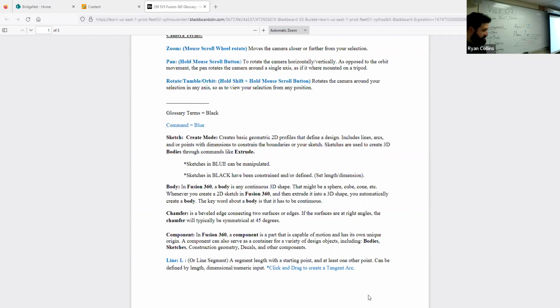The reason for this is how Fusion interacts between different objects, different components, to make something move, a joint, something like that, which is literally making something move, whether or not you actually have a screw in that place or a pin or whatever the function is, doesn't matter. It has to be between two different components. So those can each have their own sketches, their own bodies, all that such.